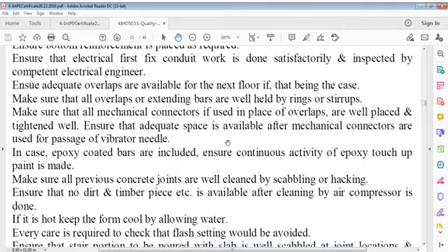And if you provided epoxy coated steel, in that case overlaps must be provided, or connectors. If you have provided it, you have to use touch-up paint for repairs, because during work it strikes corners and such things. That's what I say.